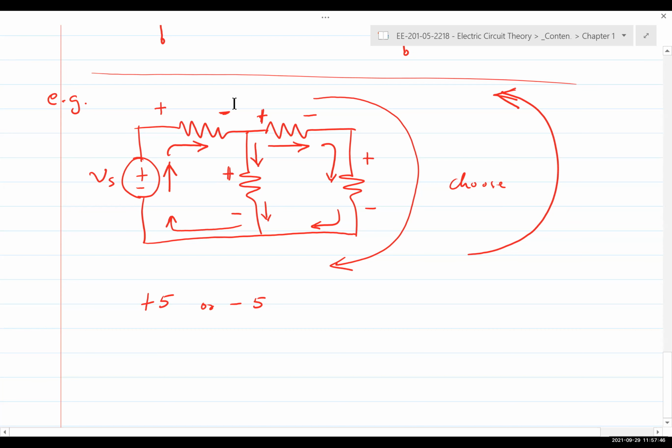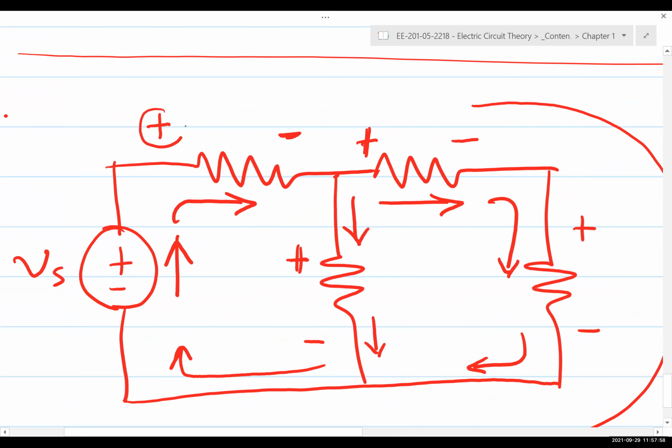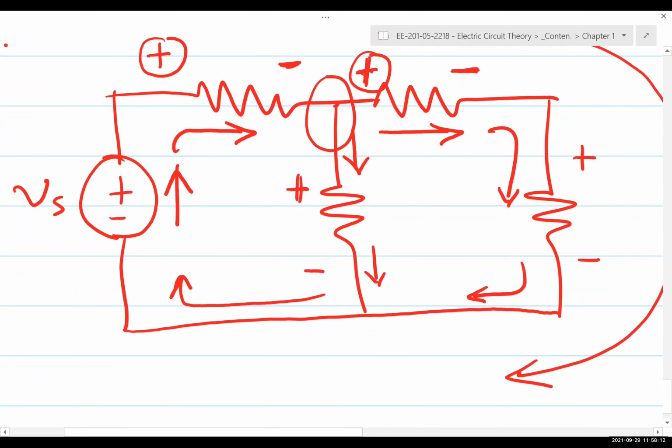In relation to the other side of it. Exactly. That's the perfect answer. So the minus sign that we see here, let's zoom into it a little bit. So this minus sign is only with respect to this point right there. And this plus sign is only with respect to this point on this side. For all other reasons, for all the references, this node is exactly the same, right? Does not make any difference. It's exactly the same. So there's a minus and a plus in there, but again, it's a reference point. That minus is lower only with reference to the plus sign on the left, not with anything else in the circuit. And that's why you have a minus and a plus in there.